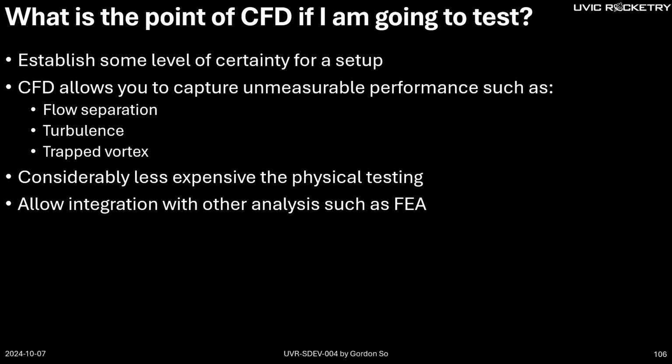It also allows you to do integration with other analysis like FEA. This is what we call FSI. And you can even do an iterative FSI, where you first use your CFD result to determine the deformation of your actual object using FEA, and then feed that deformation back to the CFD to do another flow simulation until they converge. So that's something you can do with CFD.